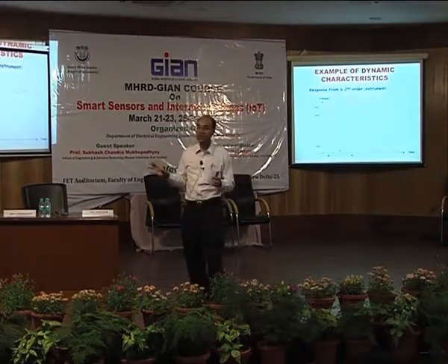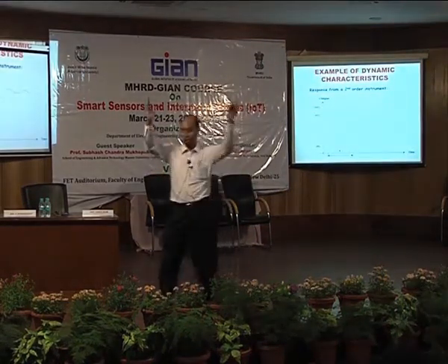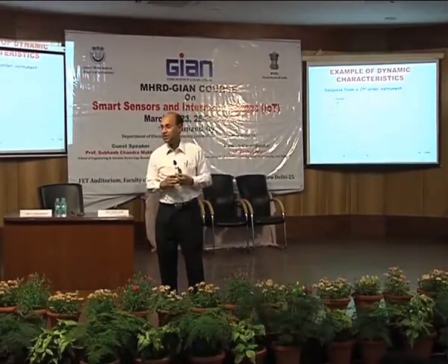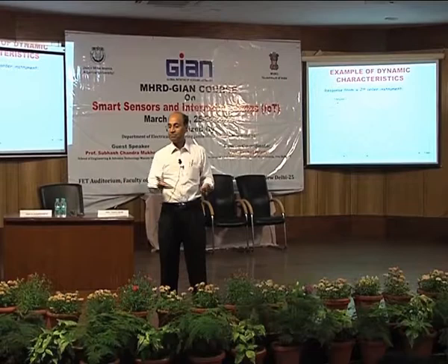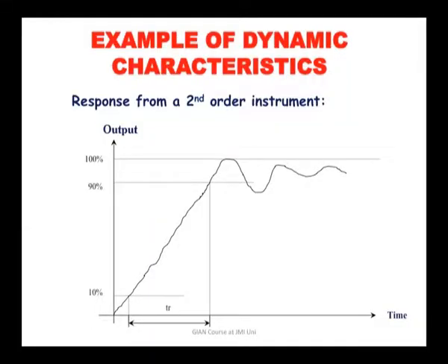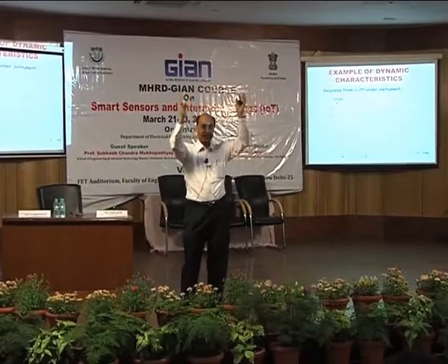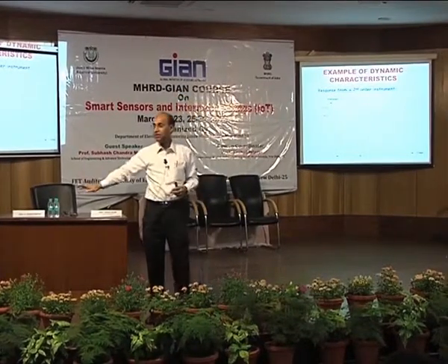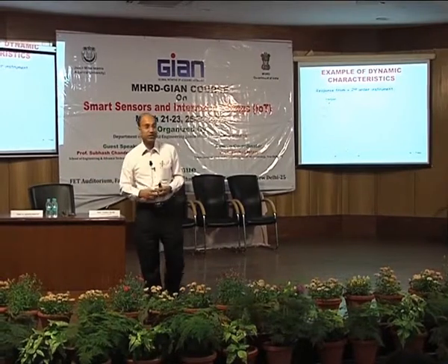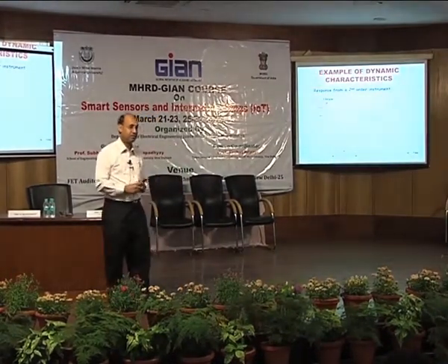You cannot control the vibration. So they make two structures to control the natural frequency of oscillations. So when the vibration occurs due to the earth, due to anything, earthquake, tsunami, whatever it is, they can actually change. They connect something with a spring damper, so they can change the natural frequency of oscillation so that it will not be close to the actual oscillations of the system. So that type of thing.